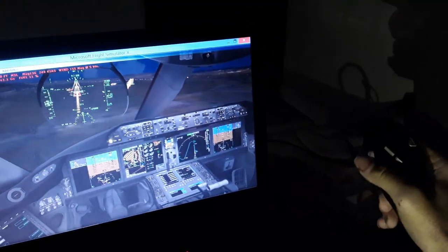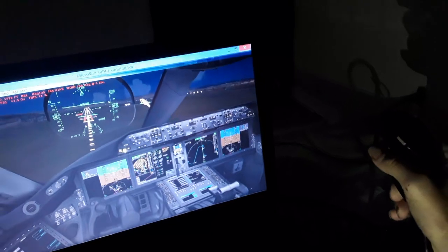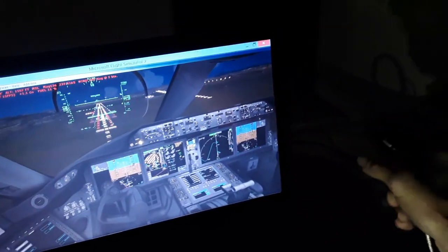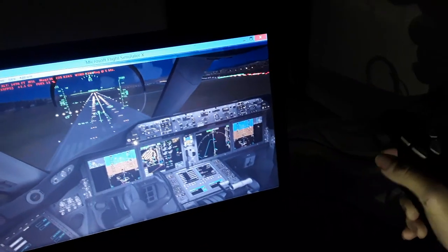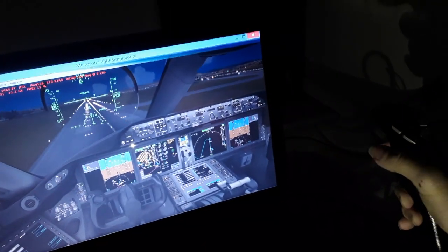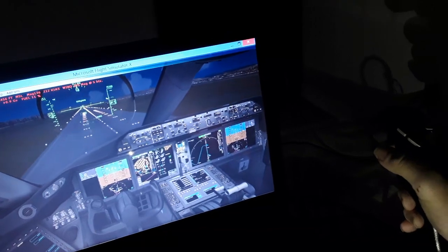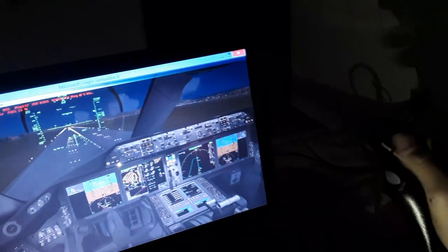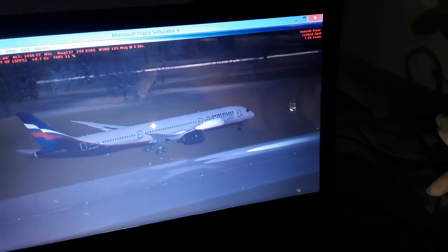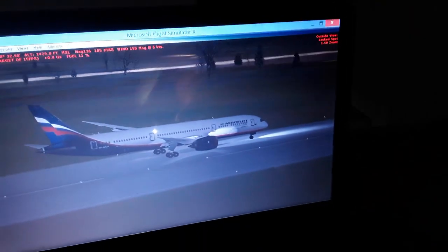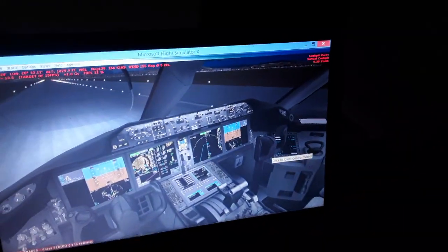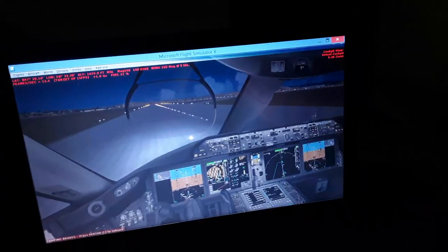Idle thrust also, because we are almost ready for the flare of the aircraft here. Increase the rate of descent. So we're going to be having the flare now, a couple of seconds, as you can see. So we flare. This is a flare, touchdown. Beautiful flare and touchdown, parking brakes and thrust reverse. Idle thrust with thrust reverser over here, as you can see.